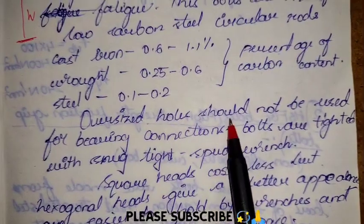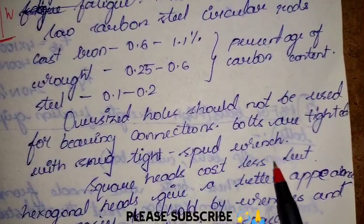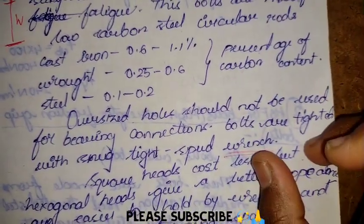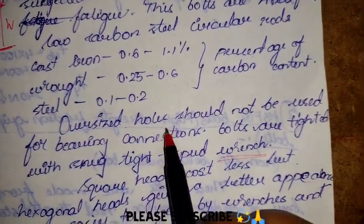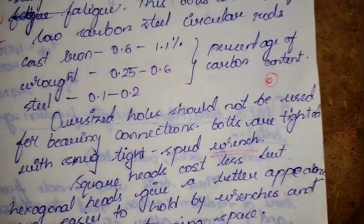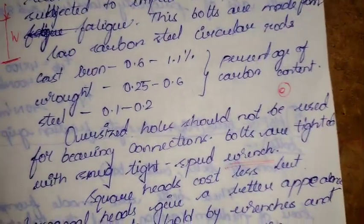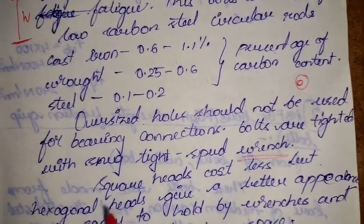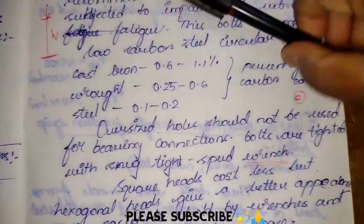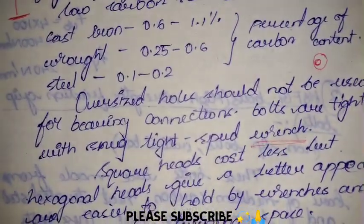Next, oversized holes should not be used for bearing connections. Bolts are tightened with a snug tight spud wrench. Here the wrench is fixed, as this is an ordinary bolt. That is why the hole that is made should not be of greater size. The hole should be such that the bolt just fits in. Here we are using a snug tight spud wrench, the wrench that is used to tighten the nut, to fix the nut in its place.